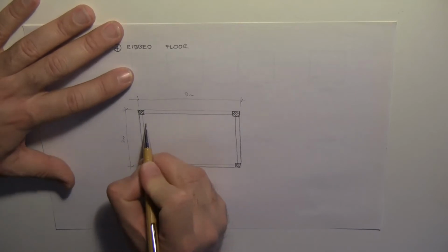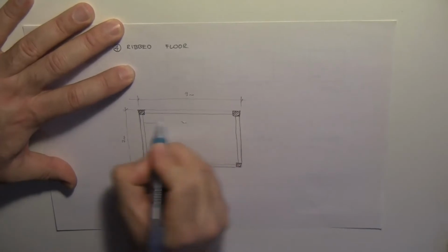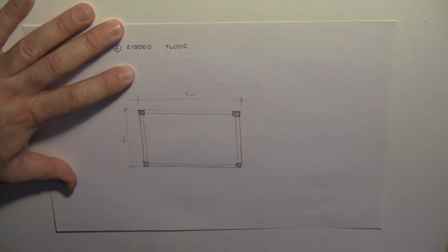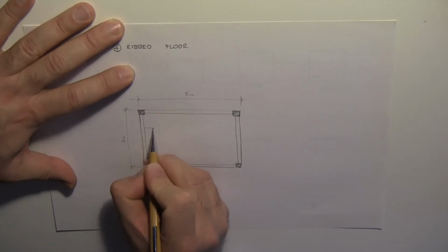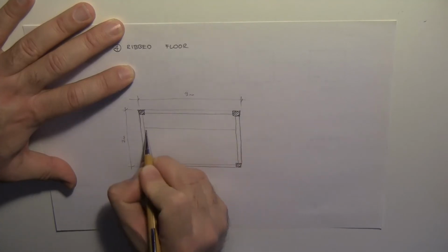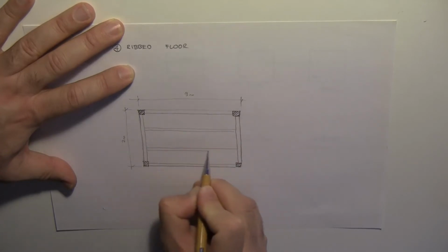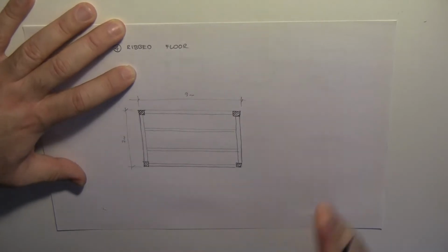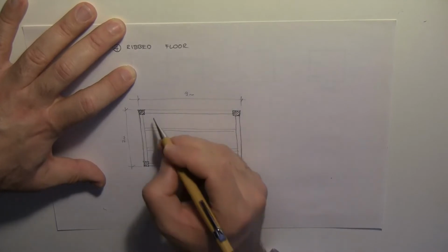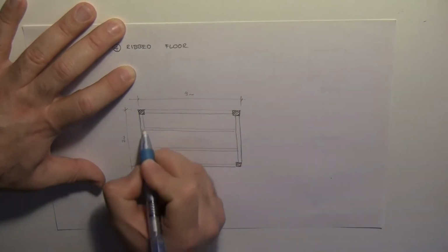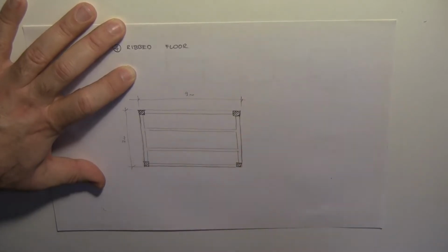And what we do, we connect the, okay, this is maybe too near. I'm going to erase it like that. And I am going to divide the 7 meters into 3 equal pieces, and I'm going to add 2 beams here. They are not ribs anymore, they are beams. And on top of them, what do I have? I have all covered with a plane of reinforced concrete, a reinforced concrete slab in fact.